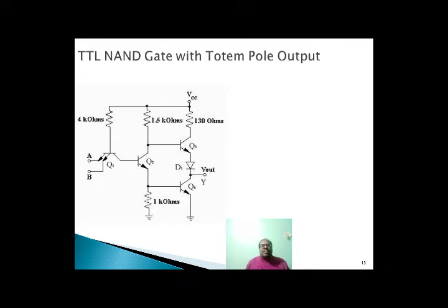Here also it is like that of that one only, but the major thing is that here there exist 4 transistors, Q1, Q2, Q3 and Q4, and one collector voltage, and 4 resistors, R1, R2, R3, R4, and 2 inputs, input A and input B, directly connected to the emitter junction of the Q1 transistor, and in between Q3 and Q4 there exists a diode D1 for switching operation.